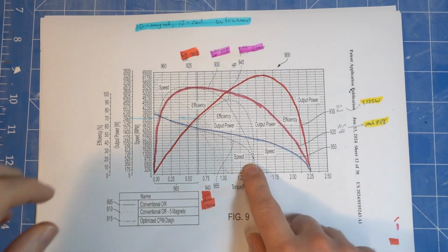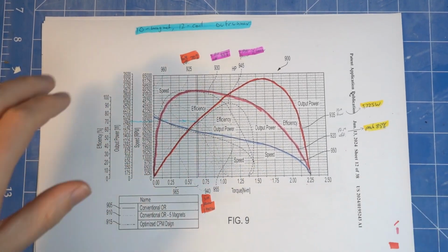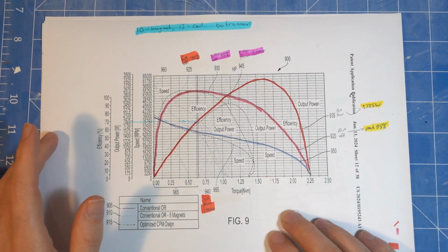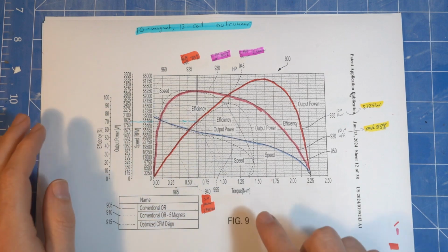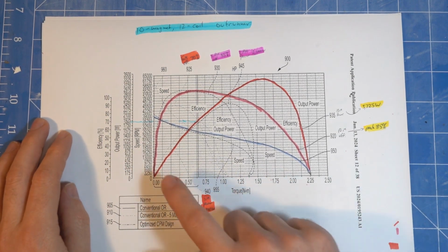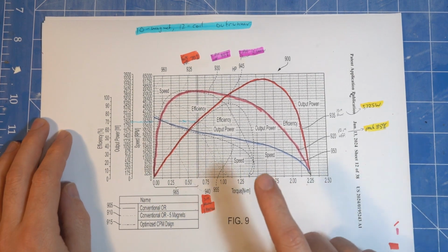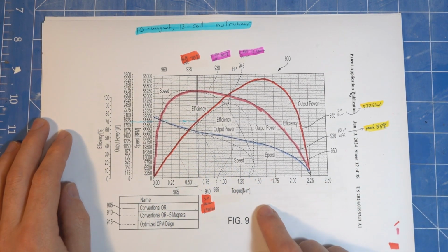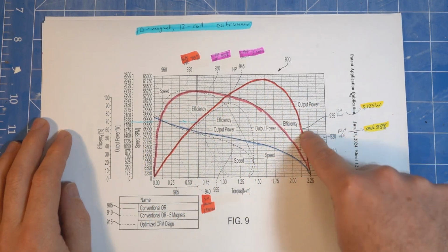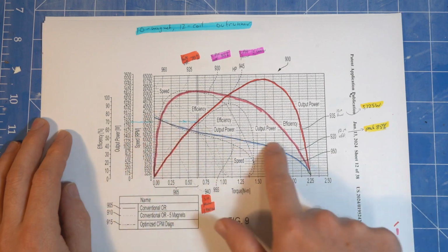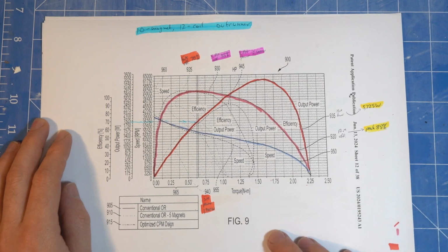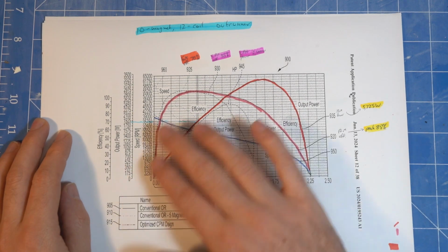This is a dyno graph for a brushless DC motor, and it's published by Milwaukee for their Milwaukee M18 tools. As far as I know, this sort of information isn't available anywhere, so this is an absolute goldmine for anyone that likes to nerd out on tools. The motor dyno graph has the efficiency, power in mechanical power, and speed as a function of the load on the motor in torque. So it gives you amazing amounts of information.